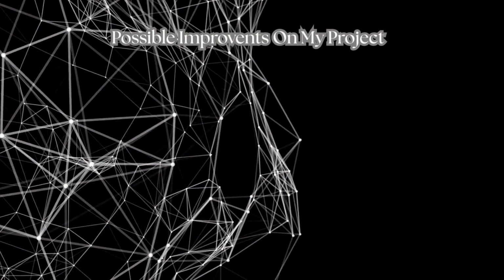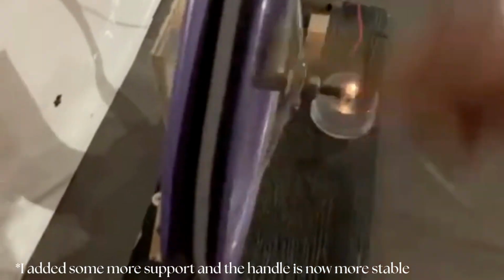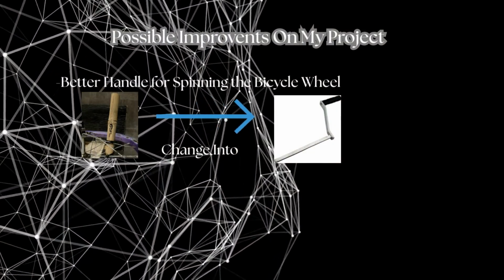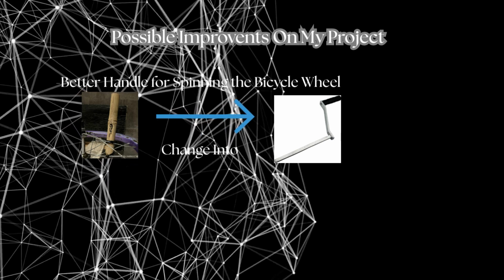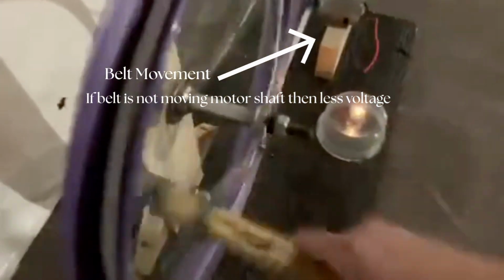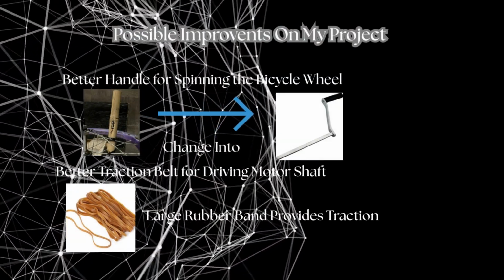First, I will make a better handle for spinning the bicycle wheel. This is because the current handle I'm using often shifts positions under pressure and lacks an ideal grip. To fix this, I could make a handle crank, which allows for better grip and efficient turning. Another improvement I could make is using a better belt that has more traction. This is because the current belt tends to fold and bend at high spinning speed. To fix this, I could use a rubber band for this belt.